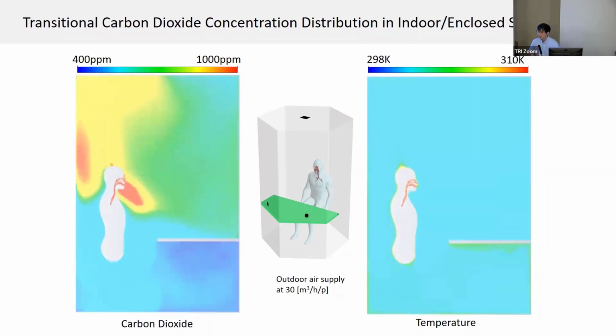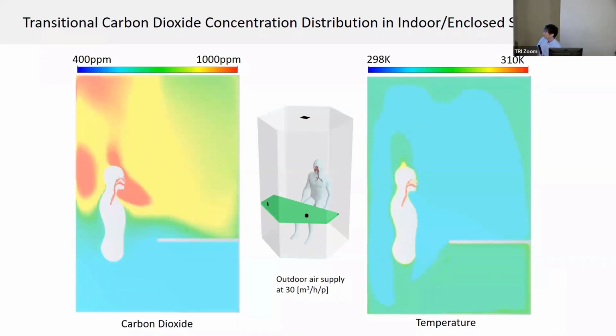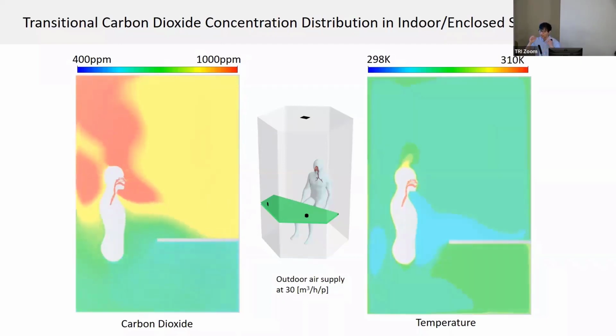I would like to say that for CO2 concentration, even if the average or representative concentration is precisely controlled under 1000 ppm, unfortunately our exhalation air contains approximately a few percent CO2. Therefore, a relatively high CO2 concentration field is formed around your face.